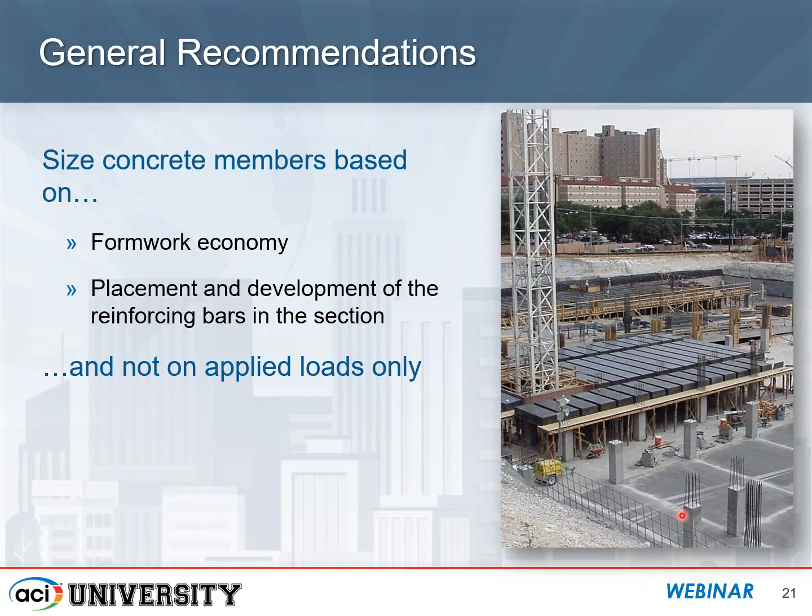When I was practicing, I did a number of peer reviews through the years, and you would be surprised what you would see in some of these particular structures. Not saying that anything was unsafe, but I recall offhand a 3-story building where the size of the columns changed every floor. Okay, that's certainly not the most economical or constructible thing to do. Same with the size also changed on a particular floor based on the tributary area of the column.